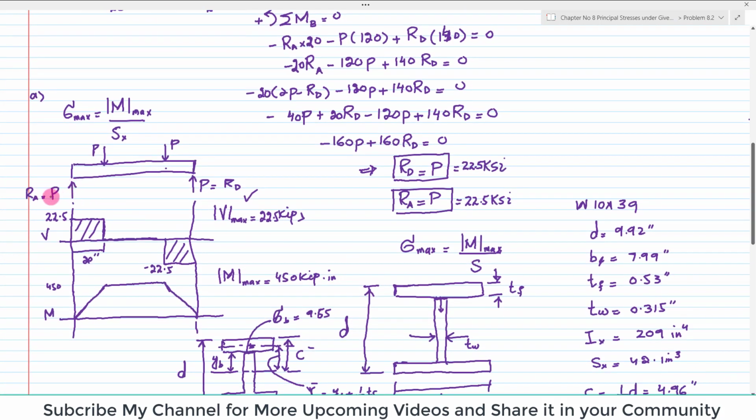So you can see here RA is equal to P, which is 22.5. So let this point be 22.5. From this point till this point, in this section, this will be P, which is 22.5. Now at this point B, clear, this is plus 22 and this is minus 22. So at point B, the shear force will be 0.